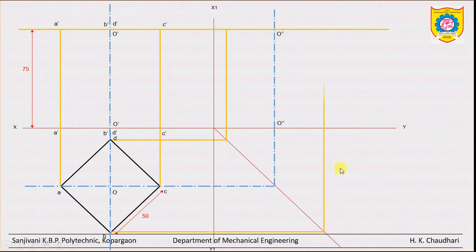Similarly this projection. Just like this front view, we got the side view. Now label the respective points: as it is the line projected from A, it is A double dash, then B double dash, C double dash and D double dash. Similarly for the top surface, just label.